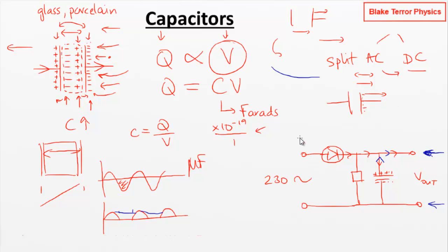This is one of the things we're going to quantify in the next video when we get onto the maths. But you're going to start filling in these gaps between these AC peaks, these remnants that have been left by the diode. So you're getting something which is beginning to approximate DC here. It's got a ripple on it because now it's going to go down a bit and then up, and then down a bit and then up, because we're getting the AC peaks with the capacitor discharge in between. So you get this variation in the voltage, what they call a ripple voltage.